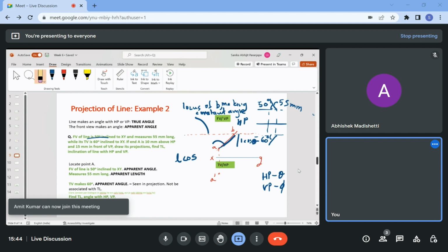So I've rotated the projection here like this, and now I know that point B should be along this projection, and it should be intersecting this line, because since I'm not changing the angle with respect to the horizontal plane, the height of point B with respect to the horizontal plane, which is seen in the vertical plane, is constant.